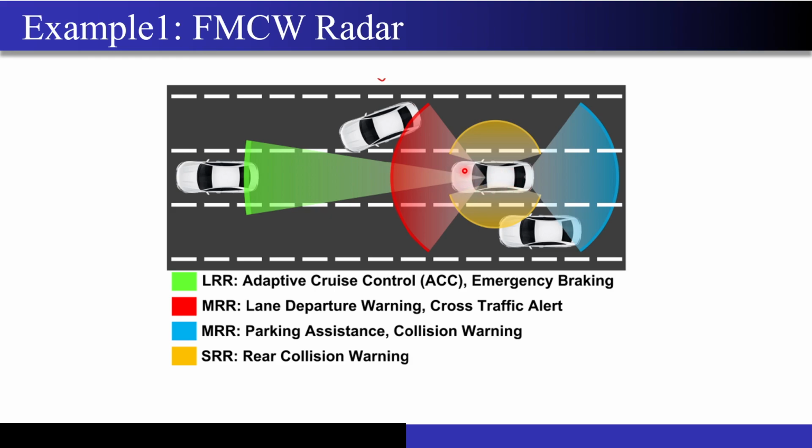and the reason for that is you want one radar which can just focus on this particular lane so that it can help you to do adaptive cruise control. What does this mean? If the speed of this car suddenly drops off, then your car should also reduce the speed immediately. Some radar will help you if another car from one lane is trying to cross onto your lane, correct?